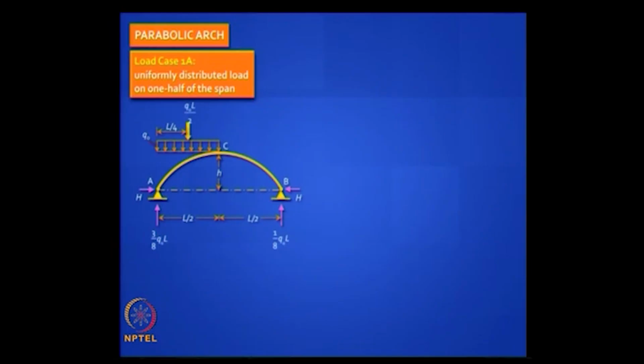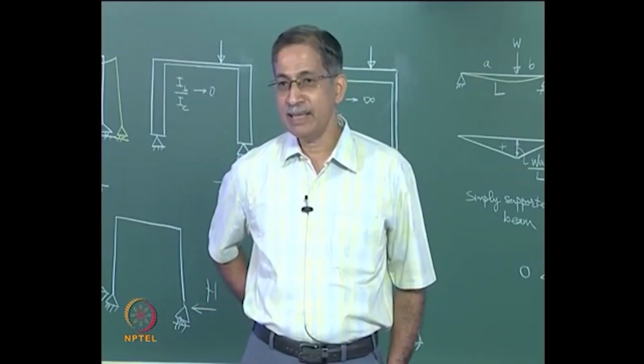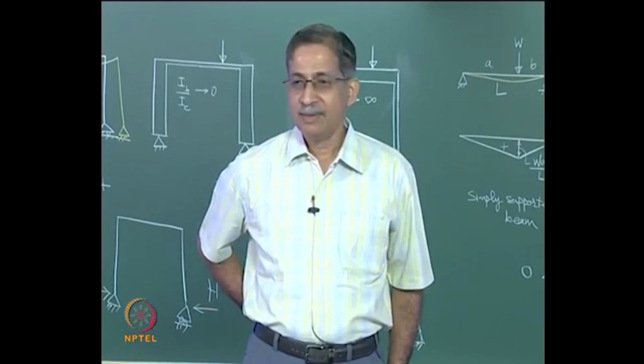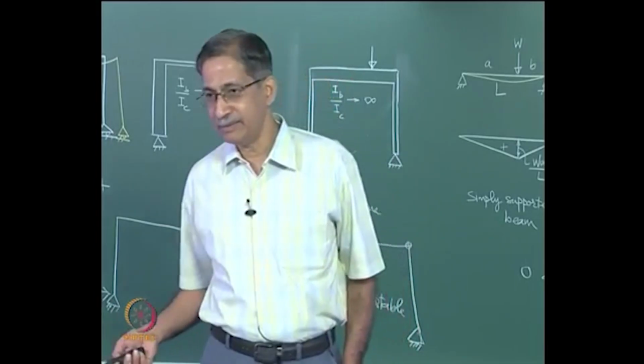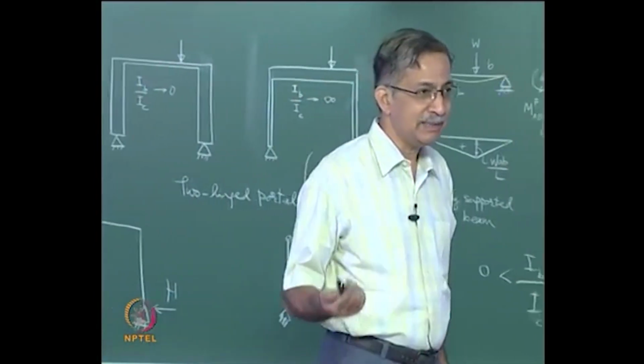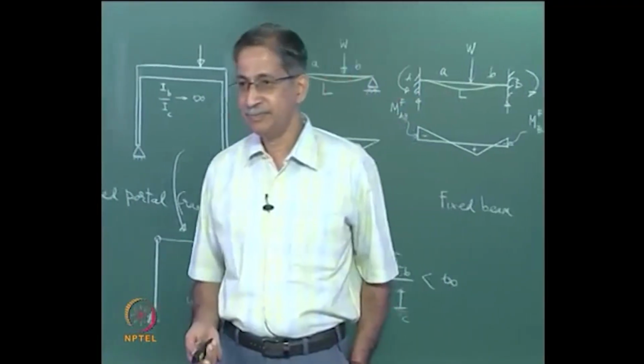Now let us do something more interesting. Let us say one half of the arch is loaded. Without any calculation, can you get capital H? It will be Q naught L squared by, there you are. And you should write applying the principles of parity and superposition. Okay. Now let us say you got it, can you now draw the bending moment diagram, axial force diagram and shear force diagram? Then only the analysis is complete. Getting H makes it statically determinate, but then you have to finish it.